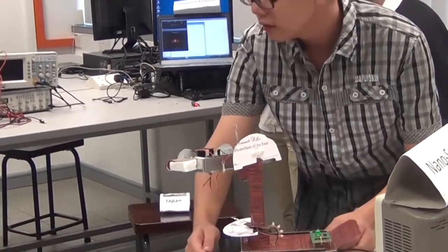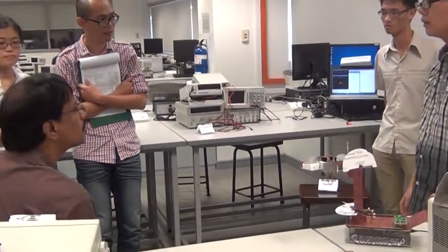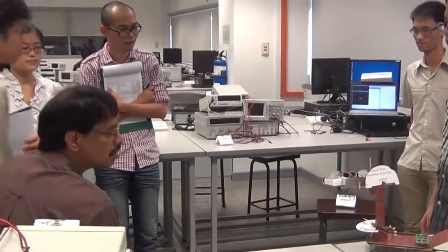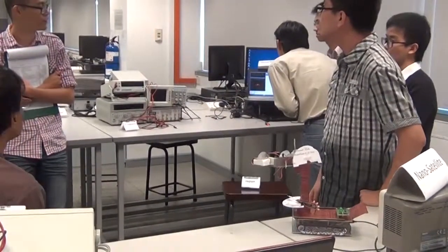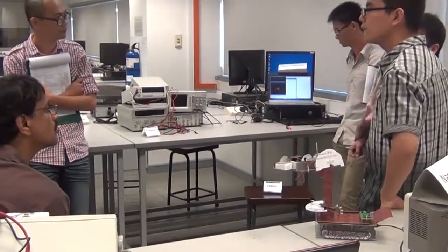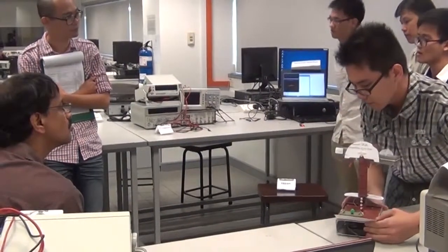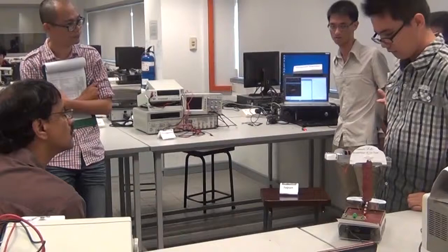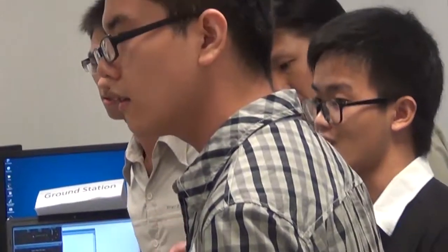Are you using a Kalman filter there? You mean the sensor we are using, right? We are using an IMU. And the IMU output is filtered through a Kalman filter and a complementary filter. What is a complementary filter? With the complementary filter, we give a designed weighting, for example, which sensor we trust more. It's a much simpler one compared to the Kalman filter. If something happens to the Kalman filter and it doesn't function, then we use this filter. So the two filters work together.